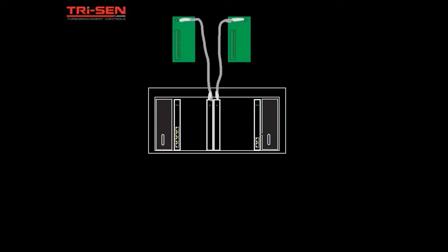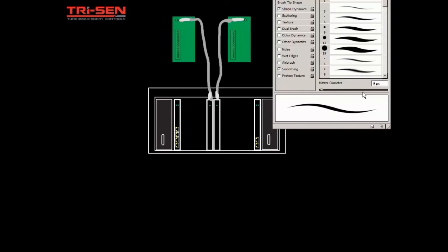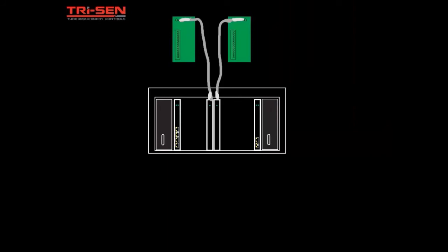What's left is to add the external networks. So we've got an I/O network, which has two cables in this system, and a host network. We use two cables for the I/O network to give us redundancy. Even though this is a simplex system, we make that I/O network redundant just for some additional security for the system. So we can tolerate a single failure of our I/O network and not compromise the operation of the system.